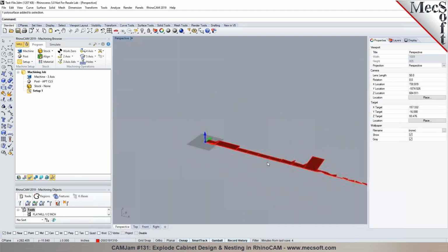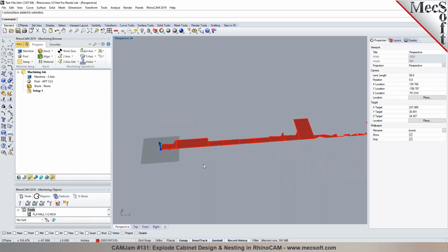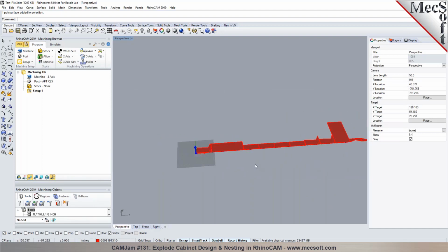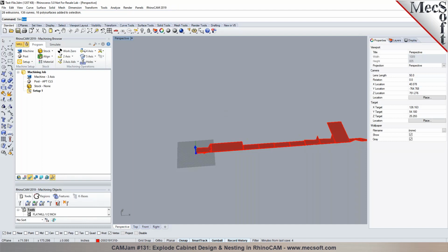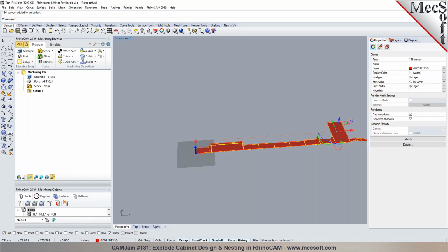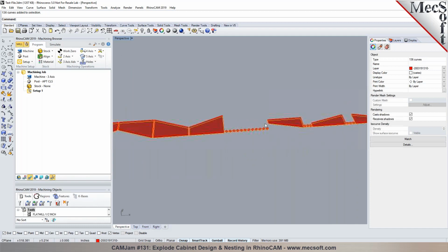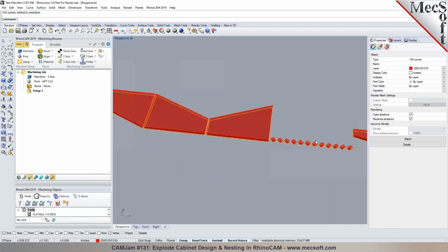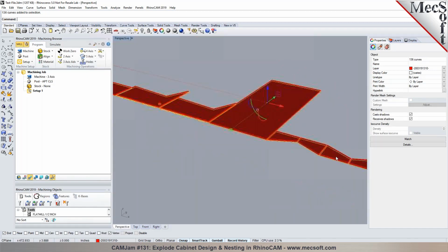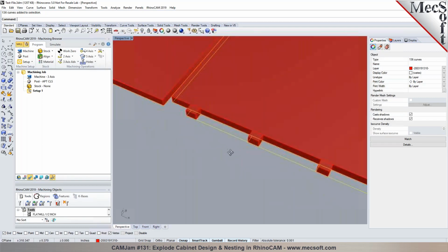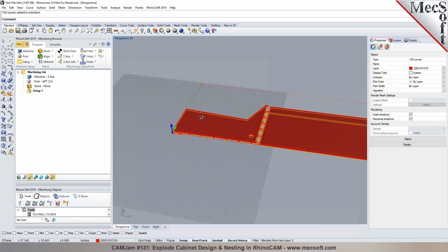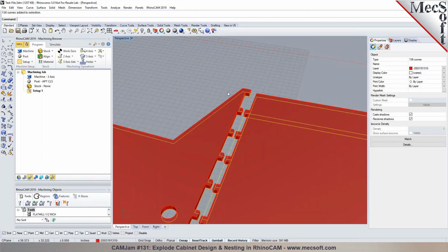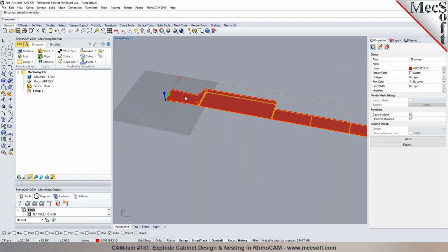Interesting. Okay. So now the parts are all flattened out in here. So if I select them all, you see there's a total of 28 extrusions and 16 poly surfaces and 136 curves. If I select the curves, you'll see it also maintains the outline around each of these parts in here. It creates those outlines for you around each of those pieces. Now, we can delete those outlines out. We can say, we don't need the outlines.